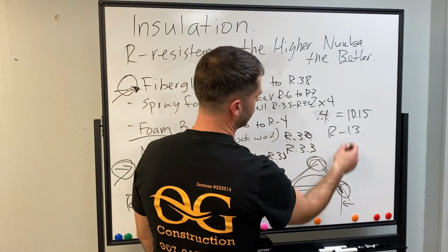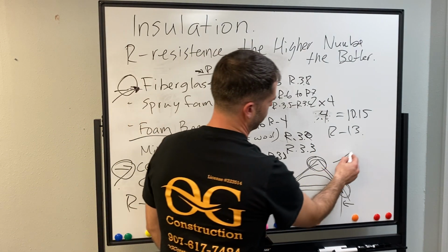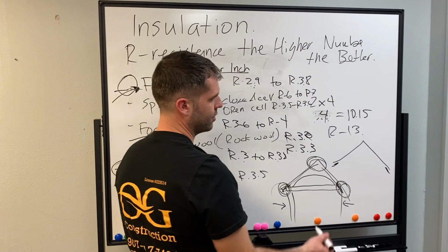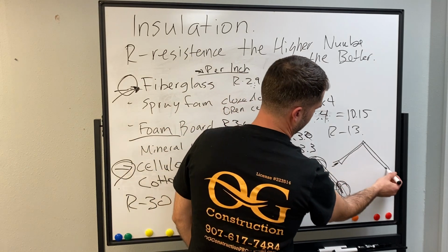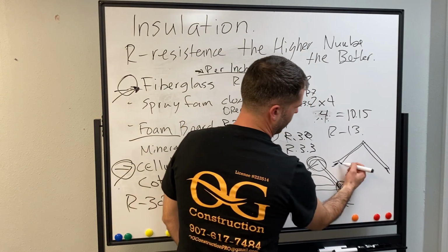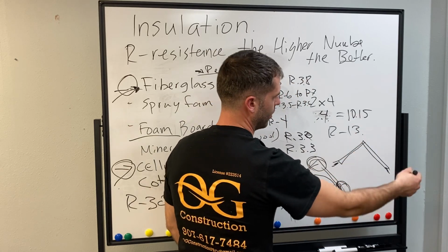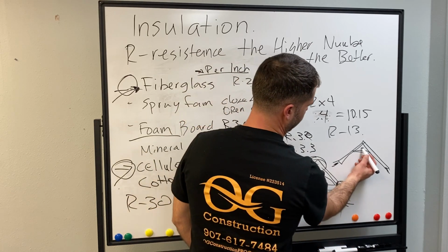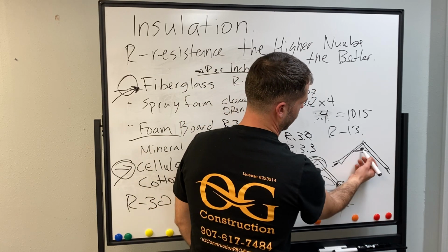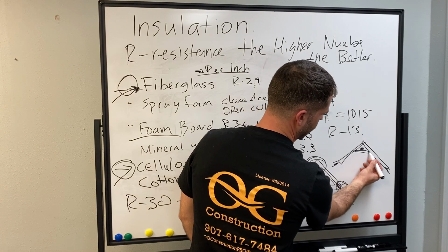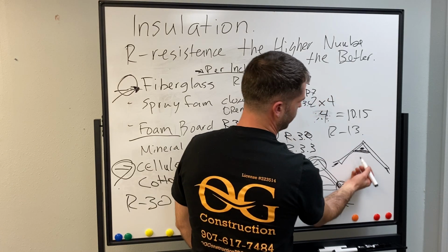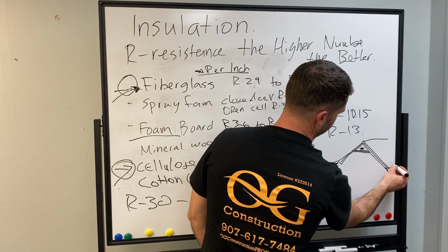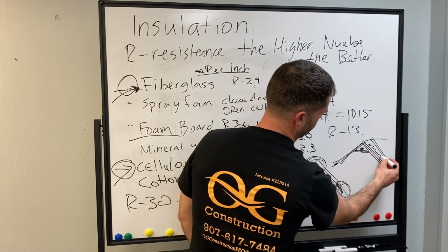Now, if you have a vaulted ceiling, you have to make sure that you insulate it correctly too, because you have breathing going on from both sides, right? You're going to have to put rolled insulation on your rafters, right? Because most vaulted ceilings have the rafters and then a collar tie right here. And people leave this open, because you can't blow in insulation there. You could put insulation in here between it, right? That's what people usually do, but the insulation will go in between the rafters inside here. This is all going to be insulation.